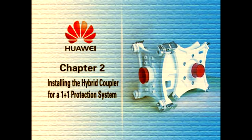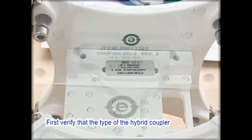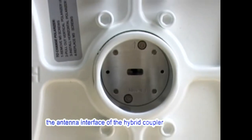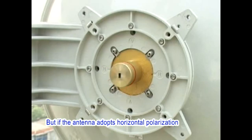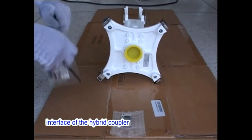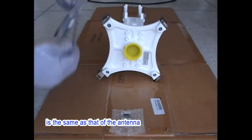Chapter 2. Installing the hybrid coupler for a 1+1 protection system. First, verify that the type of the hybrid coupler is compliant with the design. By default, the antenna interface of the hybrid coupler adopts vertical polarization, but if the antenna adopts horizontal polarization, ensure that the polarization direction of the antenna interface of the hybrid coupler is the same as that of the antenna.